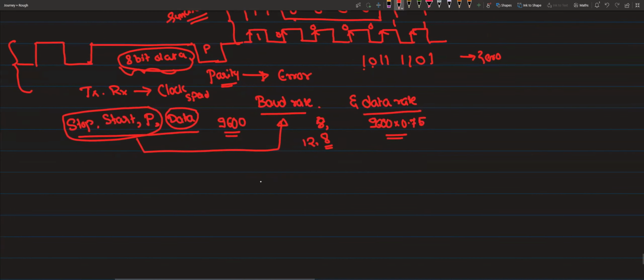And in UART, there will be multiple signals along with TX and RX, but generally we say null modem connection. We have 3 lines: TX, RX, and ground. Both sides, if I want to communicate, will have TX, RX, and ground. I will short the 2 devices' ground.